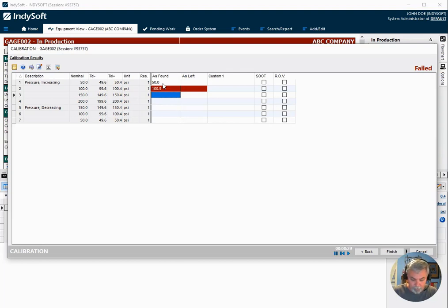Now let's say we have a significant out of tolerance, so it's outside of the 150% that you've predetermined. So if you'll notice here, not only do we have the failure, but we also had this flag as a significant out of tolerance, which means it was outside of those tolerance bands that you set for that trigger.